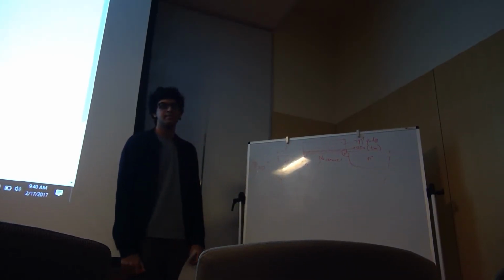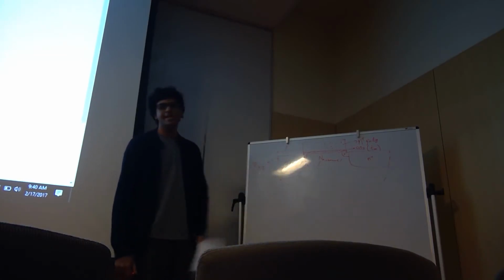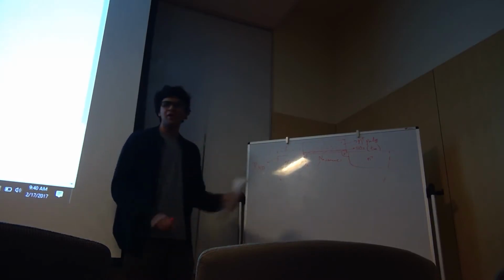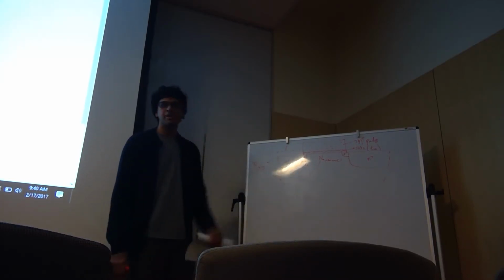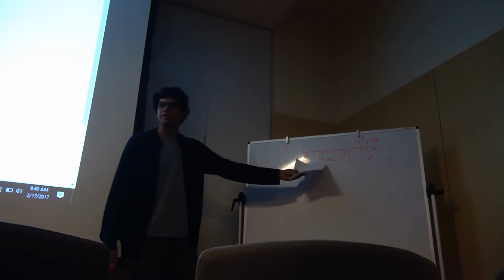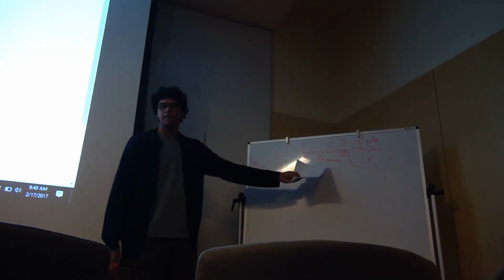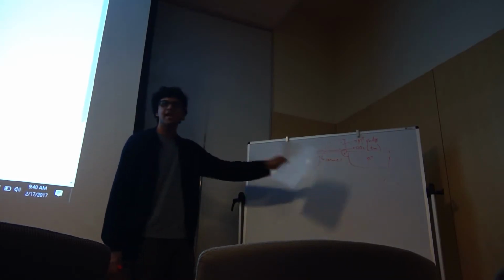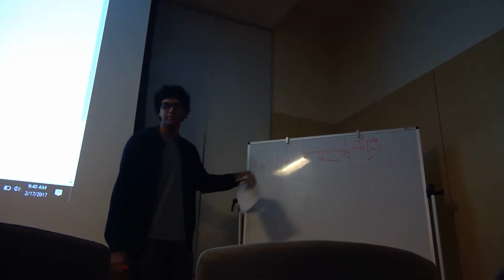I think you need to figure out your threshold voltage. Is that what you said? No. It does determine this to some extent in modern technology, but you don't have to bother. There are a lot of non-idealities here, but assuming this is a perfectly ideal transistor, only the doping of the channel determines the threshold. Yes, and your oxide thickness. I'll give the formula and then you'll understand how it depends on them.